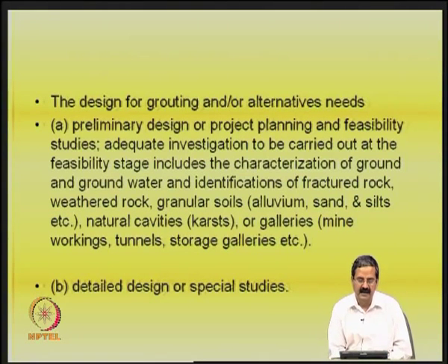When you are trying to design, you should look for certain things, particularly in the design of grouting. The first thing is a preliminary design in which you plan very well to see if things are feasible. So, you need to have adequate investigation right in the beginning, which includes characterization of ground and groundwater and identification of fractured rock.